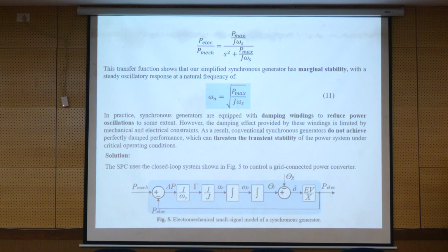When we make the simulation, we can see that if we exceed some value in the natural frequency, it swings. If we consider this in the model of the system, we can see what value of inertia we need to inject to keep it stable. When we increase the inertia, the system gets more stable. But when we pass some more, the system becomes unstable. It means that we pass this omega n.